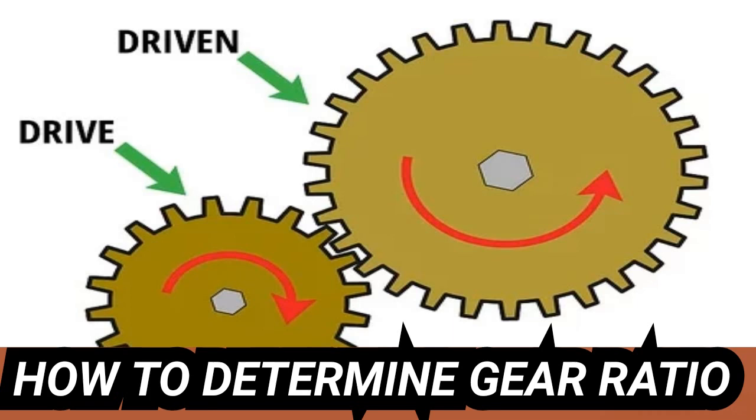3. If desired, find the gear ratios for the intermediate gears. You can find the gear ratios involving the idler gears as well, and you may want to in certain situations. In these cases, start from the drive gear and work toward the load gear. Treat the preceding gear as if it were the drive gear as far as the next gear is concerned. Divide the number of teeth on each driven gear by the number of teeth on the drive gear for each interlocking set of gears to calculate the intermediate gear ratios.